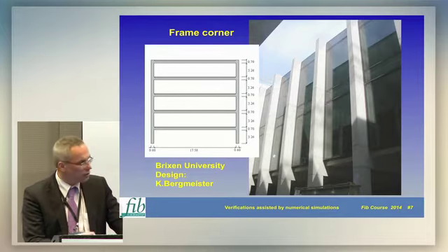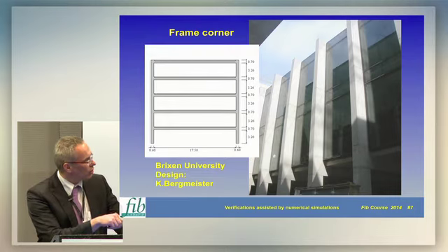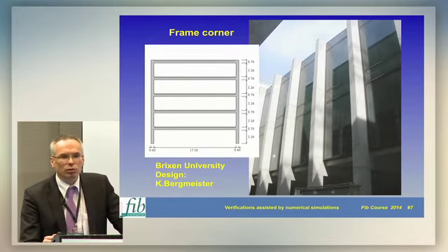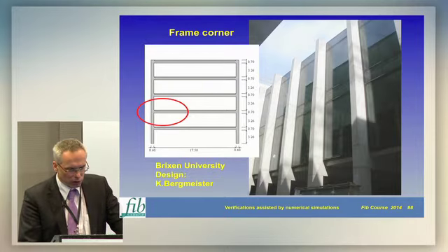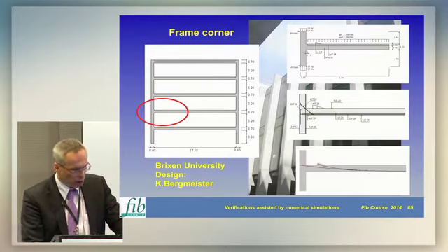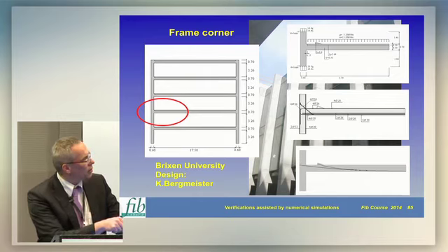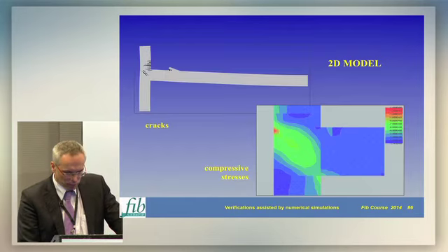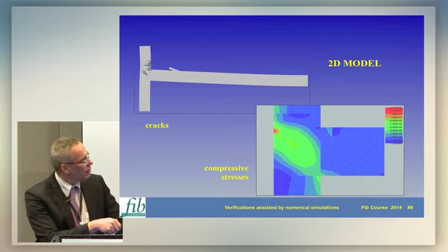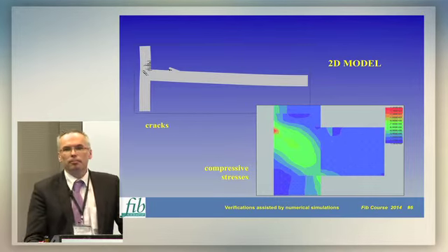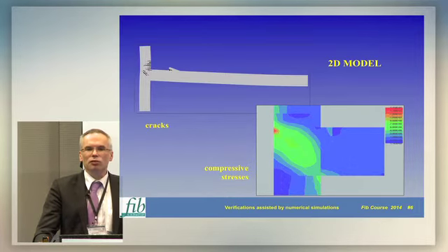So that was, for instance, this case. You see these are columns and beams. This joint is very much visible, left open to the exterior, and it is at the same time very slender, and it was pre-stressed. So here you see the normal reinforcement. Here are some dimensions, and here are the pre-stressing cables. The objective of the nonlinear analysis here was to verify the crack width in these regions so that the cracks are not visible to the public.